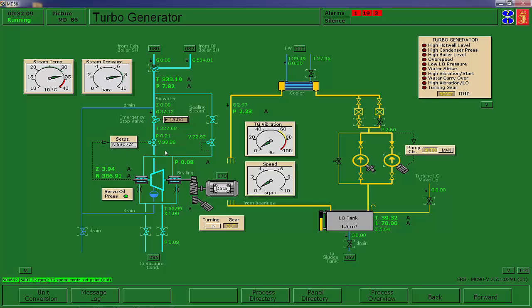And how you know that the governor has taken control is you can usually look at your lifting bar on the steam turbine. As soon as you crack it and get it moving, that turbine's going to slowly come up to speed, and then you're watching the governor, and as soon as it closes the lifting bar, then it has shut steam off to that turbine. You know you're up to speed, and then you could go ahead and open up the superheated steam from the oil-fired boiler 100% and open up this 100%.